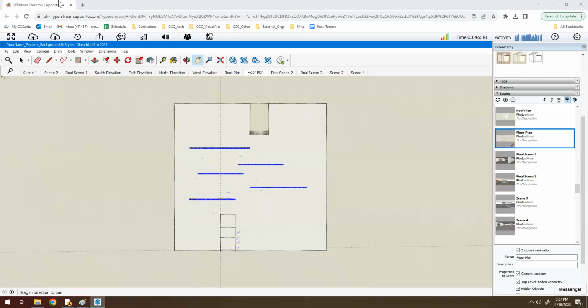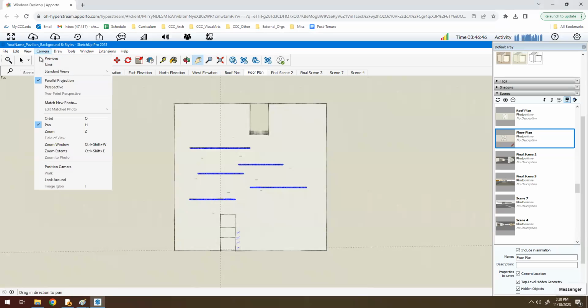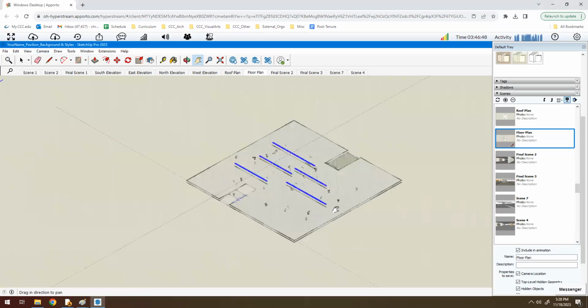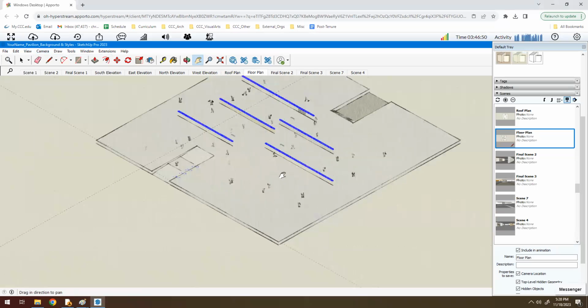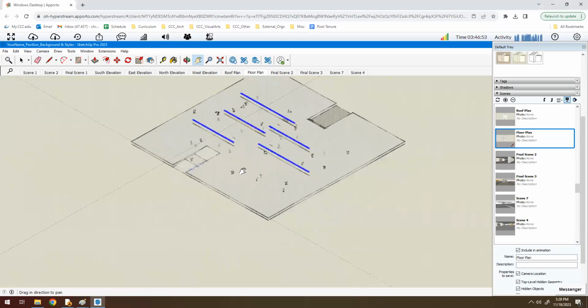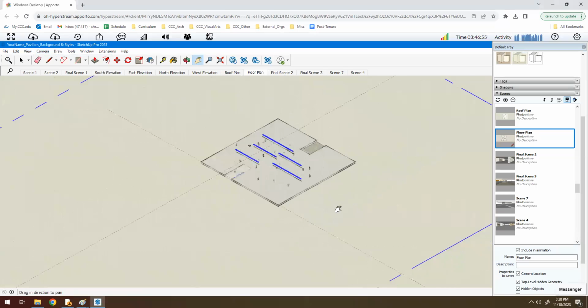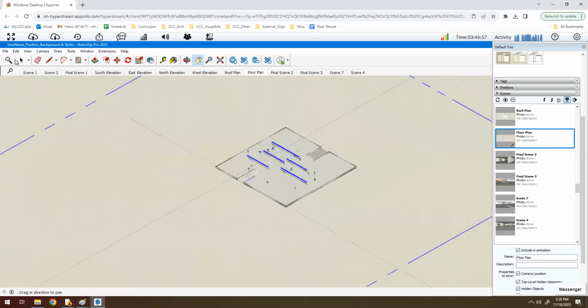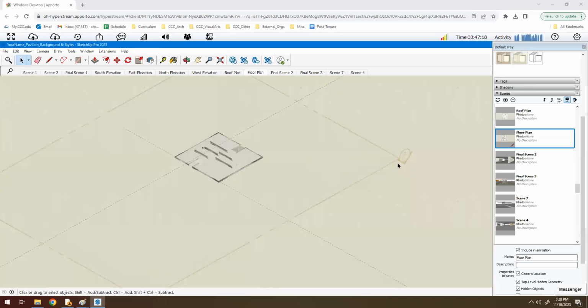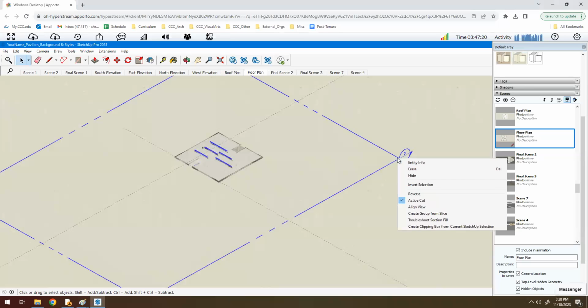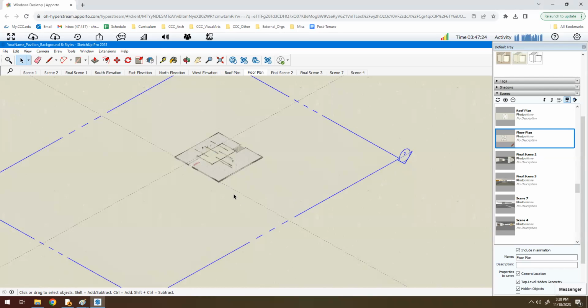Now, the second drawing that we'll generate using the section plane tool is a section. So I'm going to go back to my ISO view. All right, now you can see that it's still registering the horizontal section. And I can click on it and remove the active cut.